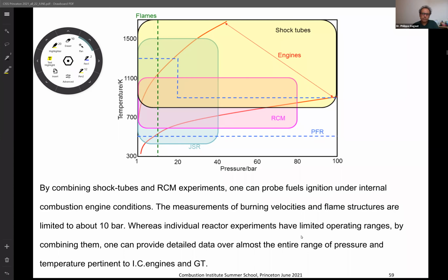Second question, could you explain the difference between Bunsen and McKenna? Yeah. Well, this is quite different because the Bunsen flame is, well, it's just a tube where you premix the fuel and air, and you form a conical flame. I will show that a bit later. You get a conical flame. In the McKenna burner, you have a porous metallic surface, and you are able to stabilize the flame above the burner, and you get a nice flat flame. And there are other configurations where there is a jet flame in the middle. But for McKenna, this is it.